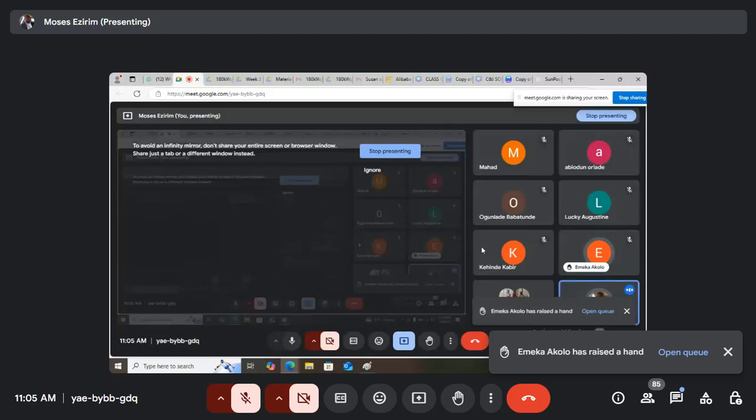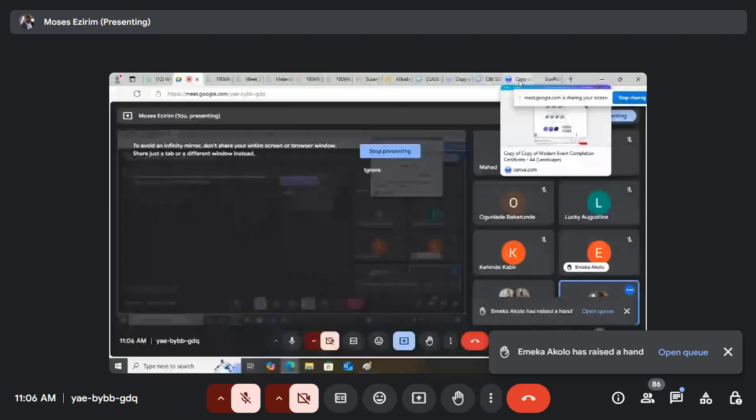Okay, thank you. If it touches the cell, the entire module will be affected. Remember, I told you that a cell forms a module through series and parallel connection. I told you that a cell has a voltage between 0.3 to 0.5. But if you check a panel, you will begin to see 20 volts, 23 volts. That means those cells have been connected in series to form a module. So even if it is a cell that is affected, it affects the whole system. Do you understand that? All right, sir. Yeah, thank you.